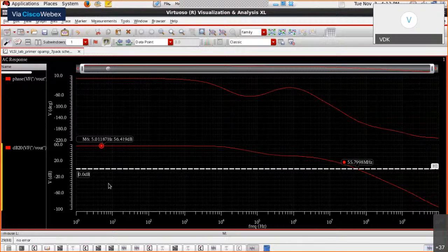And therefore, we came up with the presentation and illustration of the design of the common source amplifier with a resistive load, as well as the PMOS current source load, using the gm over ID, or transconductance efficiency, methodology of design, by first characterizing the devices to generate lookup traces and lookup tables for the transconductance, fT, gm over ID, self gain, and the capacitances of the MOSFET which are of interest to us.